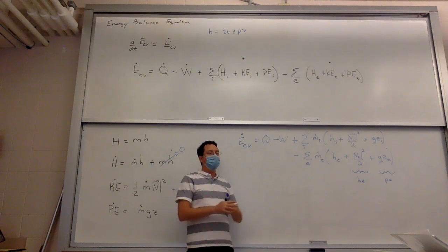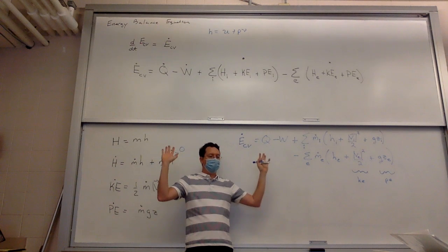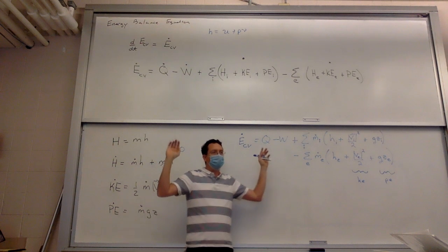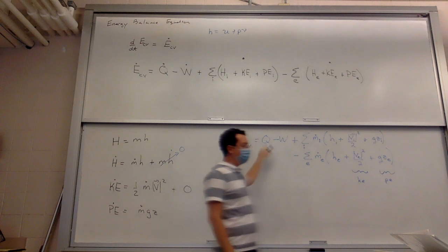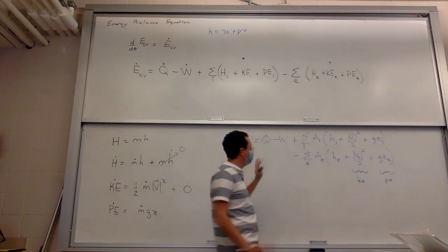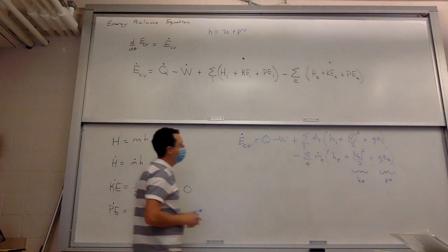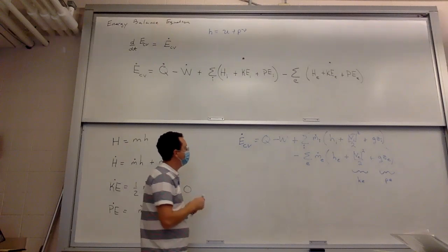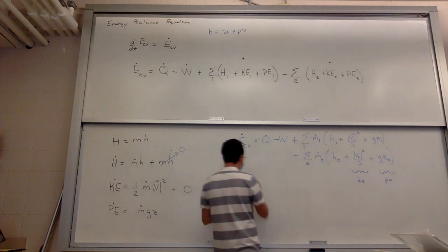If it's an equilibrium, it'd be more like you let it settle and you walked away forever, and you're not talking to it at all, right? Here, we are talking to it because we're extracting heat or work, but we're running it in a way so that inside the control volume, nothing is changing. In particular, the energy in the control volume is constant, in which case this is zero. So our equation is going to be 0 equal, so this is steady state.